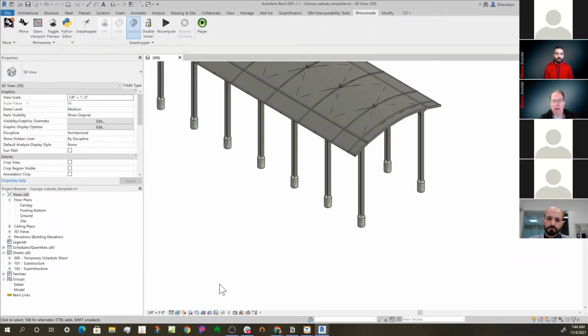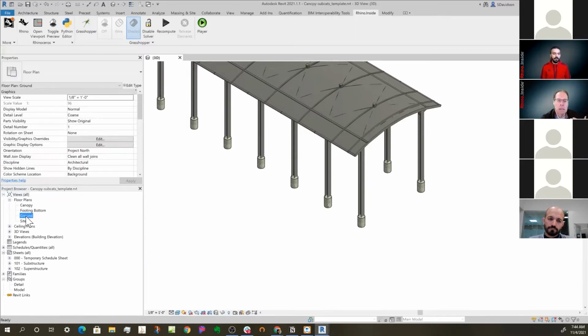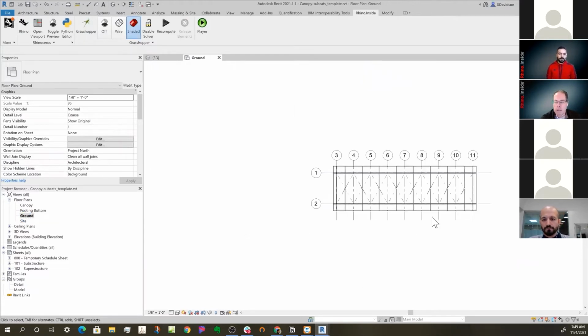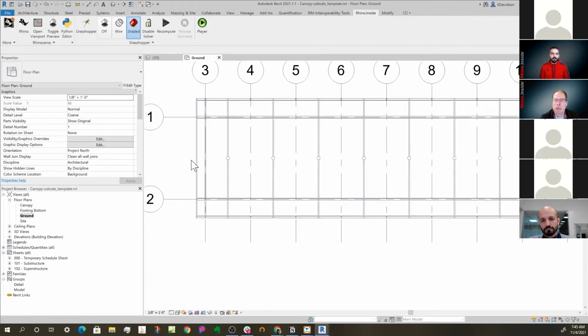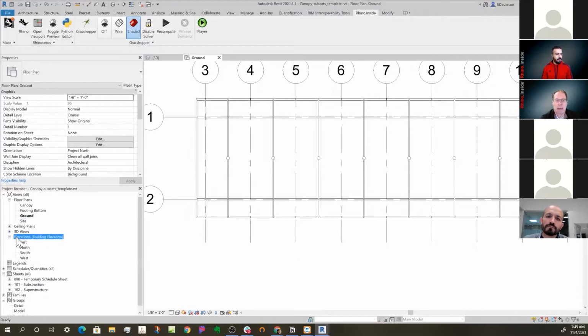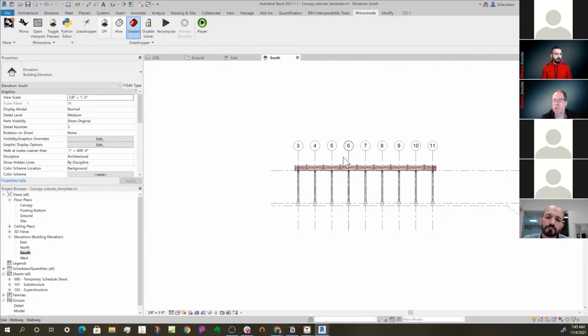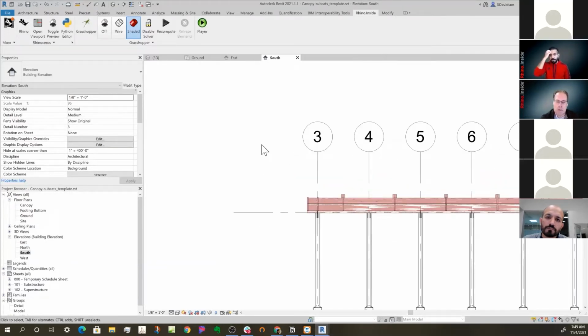All right, so we're going to get a little more complicated here, because one of the things to think about, we talked about wanting to make drawings. And so one of the things, always thinking about, how are these things going to look in Revit from a drawing perspective? When you're in Revit, the line types and how everything gets drawn and cut, and if we go to elevations here, how all that looks, that is all based on category and subcategory of objects.